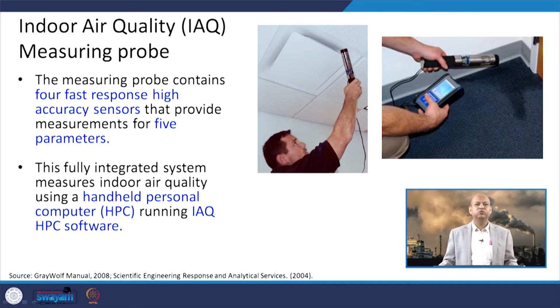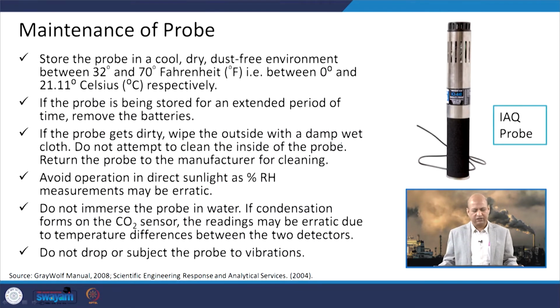If we talk about how to use this probe or sensor based equipment, anywhere in an indoor environment you can take this probe and keep it there for a certain time. It has certain reactions, and then it can give the reading of those particular components, whether it is gas concentration or humidity or temperature, etc. Plus it can record the data into this HPC, the handheld personal computer. From there we can transfer it to the desktop computer. We keep this probe for a certain period, because otherwise there is variation in the reading, and consequently we can take 3 or 4 readings and then take the average of it.